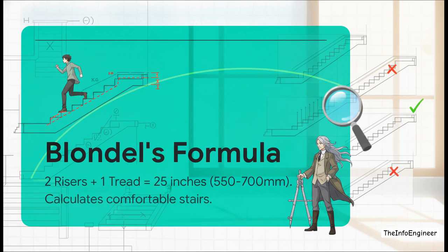This brings us to a foundational rule that is actually still embedded in modern building codes today, Blondel's formula. The formula states that 2 risers plus 1 tread, which we also call the going, should equal roughly 25 inches. That translates to an allowable range of about 550 to 700 millimeters. Why? Well, because the average horizontal stride of a human is about 24 to 25 inches. If you're stepping upwards, you naturally have to reduce that horizontal distance. By factoring in double the vertical rise, the formula inherently limits your stride length. It's essentially a geometric boundary, so people aren't forced to take tiny, awkward stutter steps or overly large, unsafe strides.